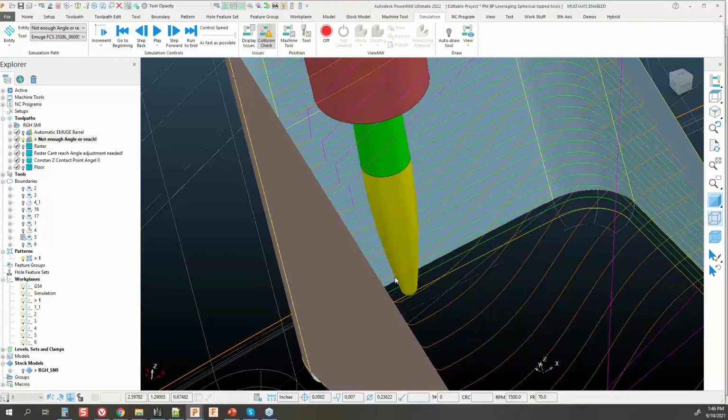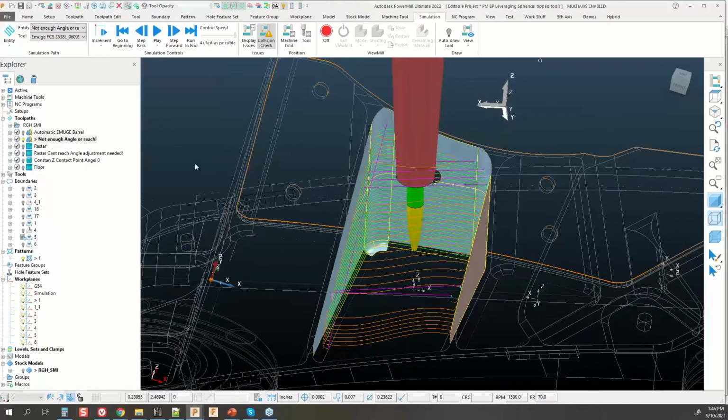When I've cut with this, the times that I've used these tools on titanium and aluminum, there are differences in both the scallop height capability that's calculated, as well as the RPMs that we use, just based off of the diameter and where we're cutting on the tool. But that is an example. I'd like to just keep that in mind at that place.